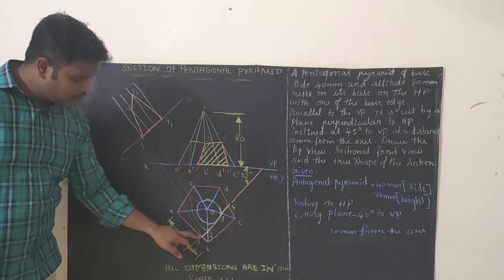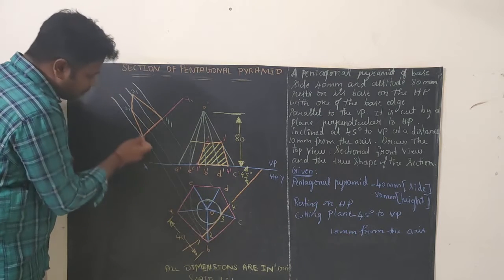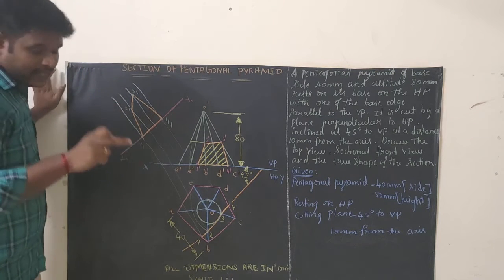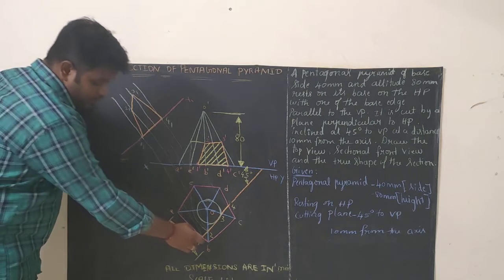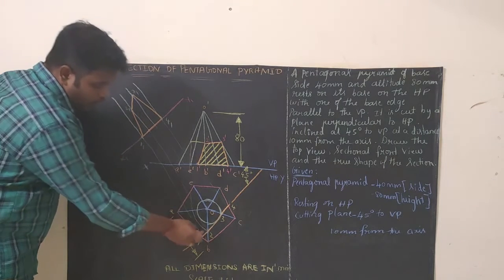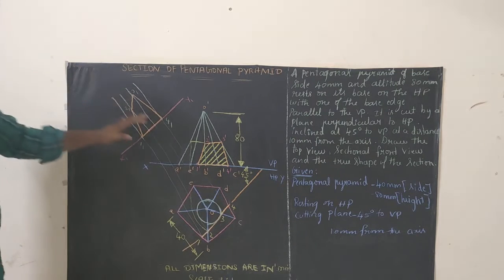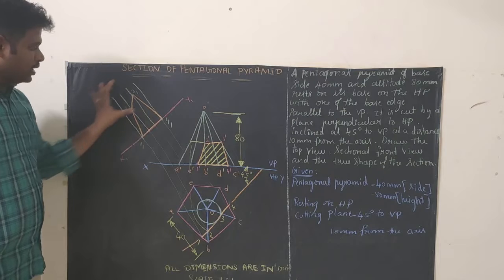Then what you need to do, these are the cutting points, right? 1, 2, 3, 4. Extend all the cutting points perpendicularly like this. Use an L-shaped scale or long scale, and from here at 90 degree you have to draw an extension line. So 1, 2, 3, 4, all the 4 lines should be extended to some distance away from the new reference line. So till here alone.